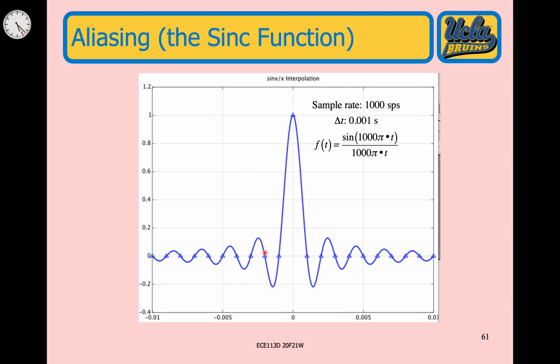It's filling in the time between the samples when you slide that sinc function by the impulses of the samples and multiply them together. All of this stuff that has a non-zero value gives you a non-zero product as it slides by.